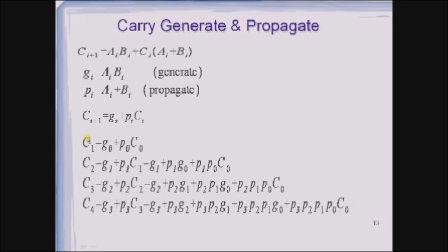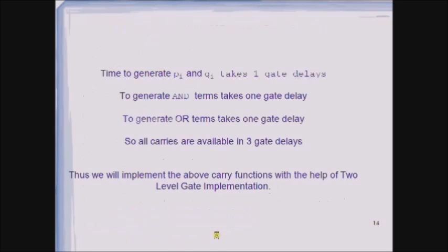Now all these carry out expressions depend totally on the inputs as well as on the carry of the previous stage. What we do is calculate all these carries at once, and give these carries along with the inputs to the circuit. Now let us implement these expressions with logic gates. Note all the carries are dependent only on inputs A, B and C.